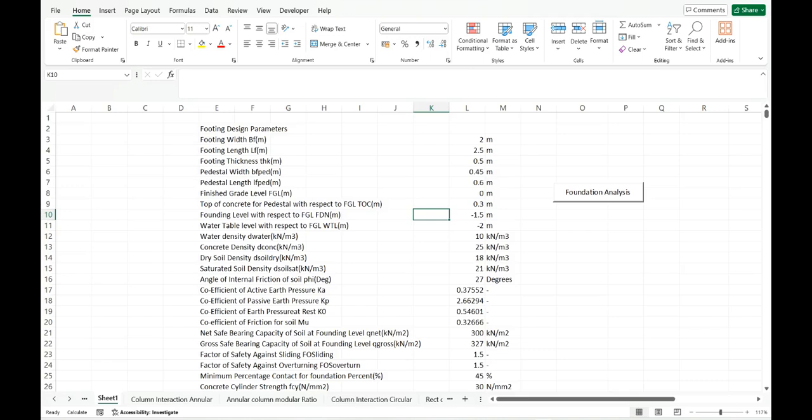For design of columns, the beam end forces are picked from an external Excel sheet using Explorer. This is demonstrated while using the program. Once these values are populated in the design worksheet, the interaction ratio is generated for a particular section size with certain percentage steel. Here in general, Bresler load contour method is used with alpha